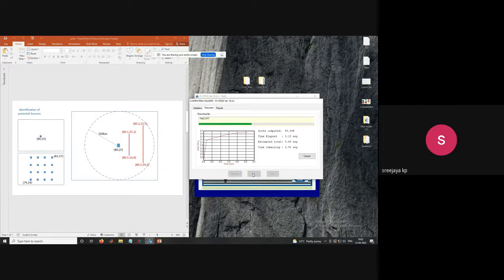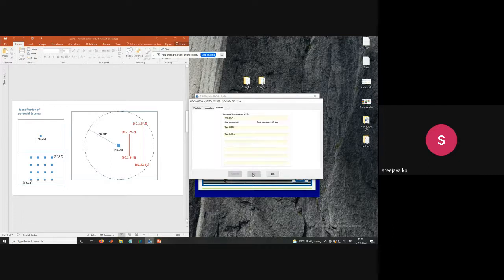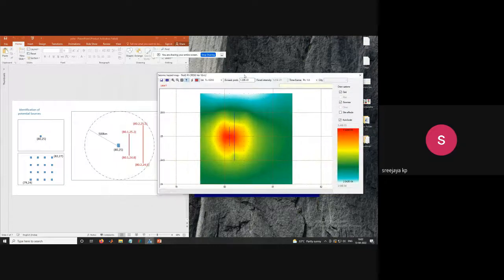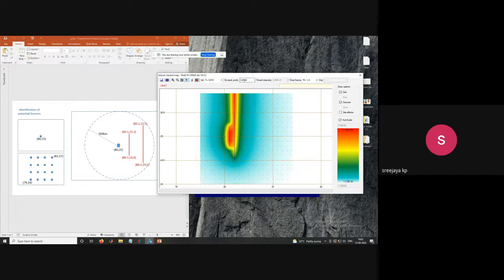So I am running it for a grid of stations. If you see the data, you can see here these are our two faults considered, and these are the PGA values at that location as a contour. I will change the return period, the probability as 0.04. For the 2475-year return period, our PGA value is like this, 0.78 g.